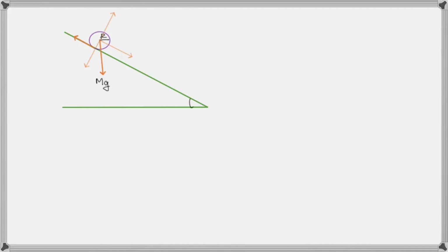You have friction. So let's go with weight is mg, and the angle is theta. The weight can be resolved into two components, mg sine theta and mg cosine theta. And then you have the normal reaction, and that is the friction. So when you calculate the torque, you know torque is F dot R, so friction times R, which is the radius of the sphere or cylinder.